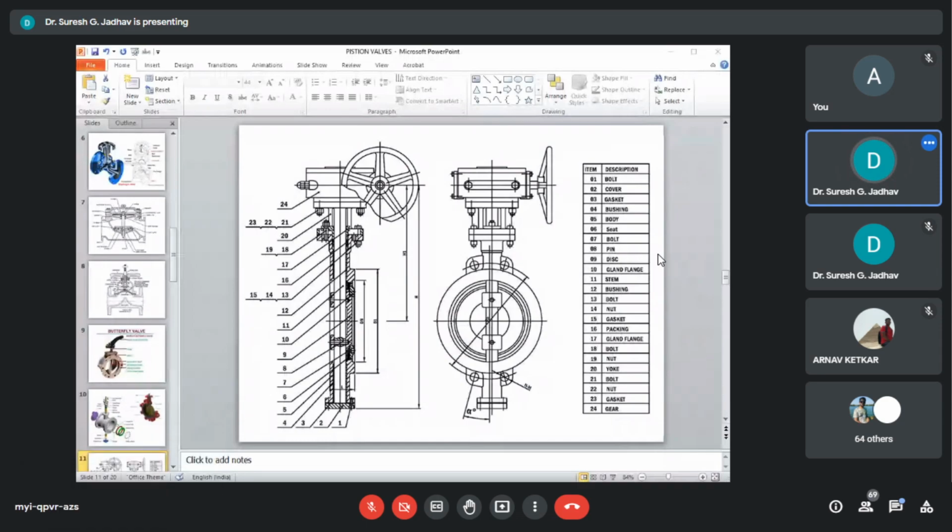Resiliency of metallic seats is used for pressure, but will not suit valves for vacuum. Seats shall be provided with extra support when used with abrasive operations.